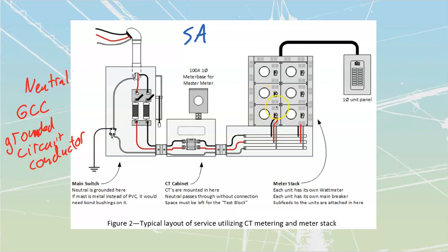And that breaker is then going to feed into a meter base. So that one through like that. And then out of that meter base, we are then going to feed to our actual conductors. And they're going to go up this section over here, which is going to be a chase way like that. Take this one, we'll do the same thing. Meter base, put that one up there, and then obviously you would have your neutral that would have come into there as well. That's going to be spliced on and carried through as well.